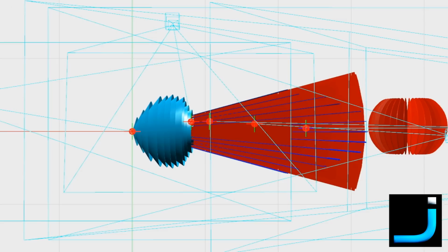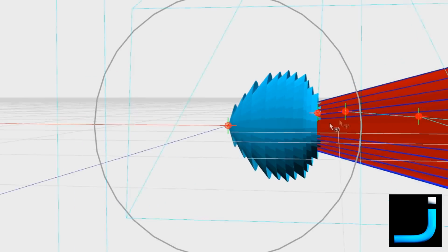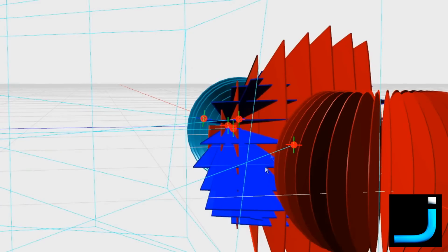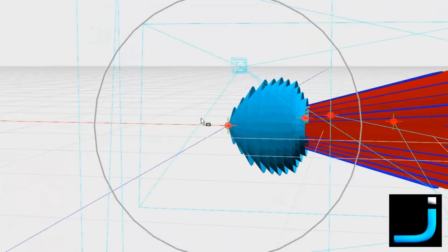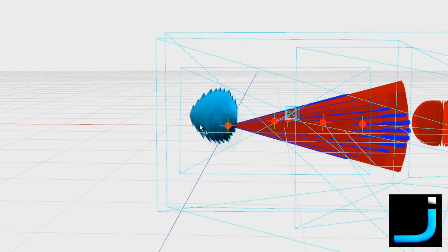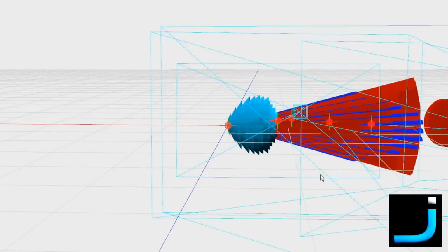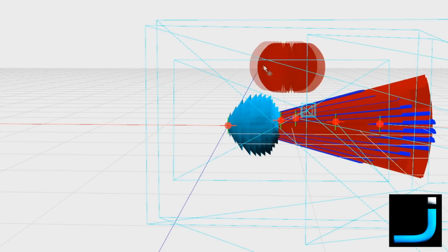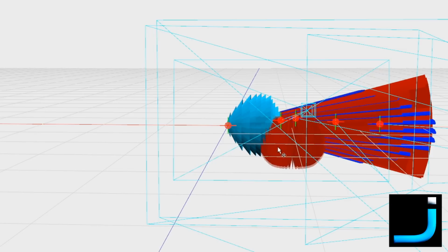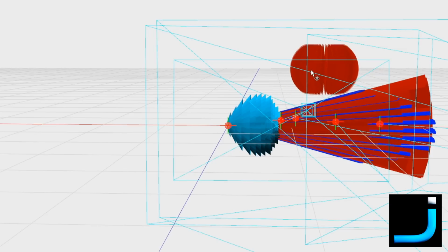You'd have a diversity receiver connected to two Yagis, one horizontal and one vertical. In addition to that, you would also perhaps have a circularly polarized antenna, which would allow you, in close range flights when you're coming back into land, to always have a solid signal, even if you were coming on your final return through some trees, for example.